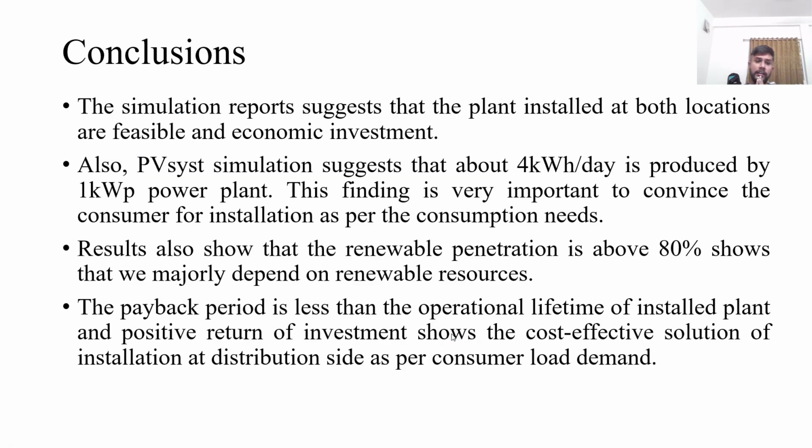So now the conclusions are: the simulation report suggests that the plant installed at both the locations is a feasible and economic investment. Also, PVC simulation suggests that about 4 kWh per day is produced by a 1 kilowatt peak power plant. This finding is very important to convince the consumer for installation as per the consumption needs. Results also show that the renewable penetration is about 80%, which shows that we are majorly dependent on the renewable resources. The payback period is less than the operational lifetime of the installed plant, and positive return on investment shows the cost-effective solution of the installation at the distribution side as per the consumer load demand.